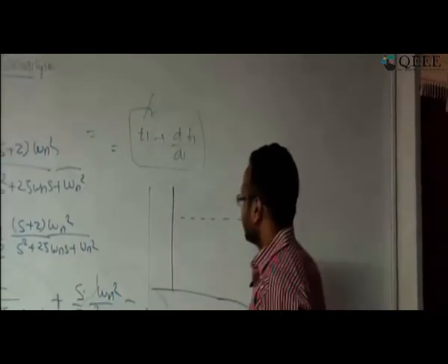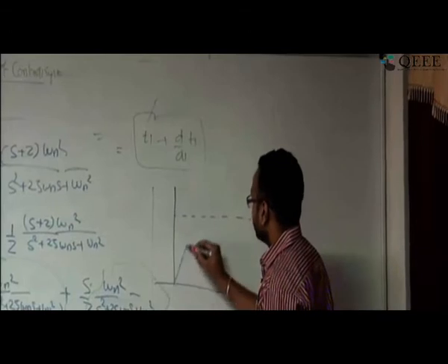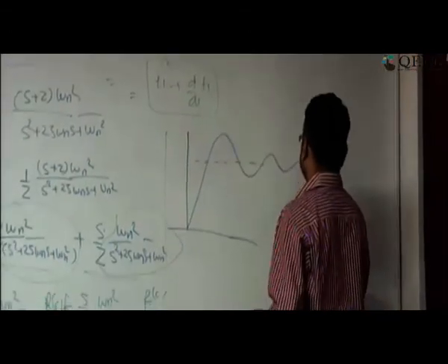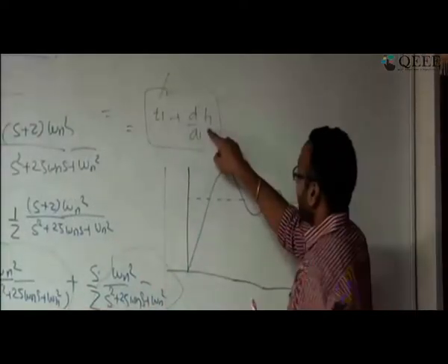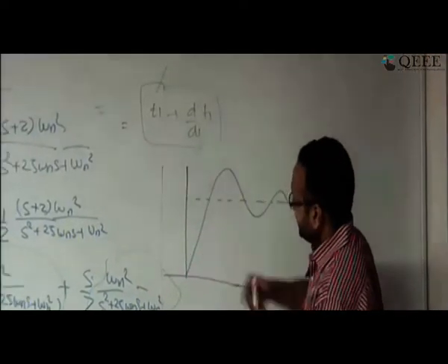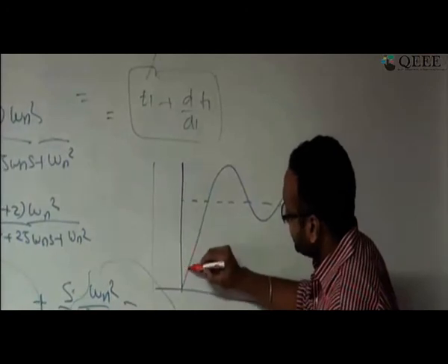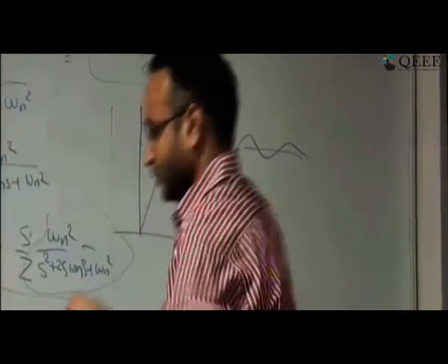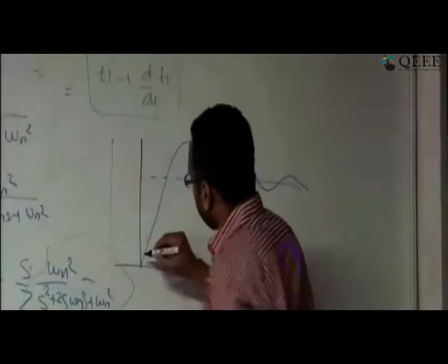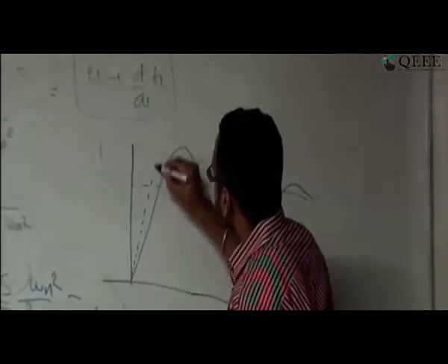This is the standard second order system, and you are giving a standard input signal, so you know the response is going to be like something. Because of the second term, the actual response is going to be this plus the derivative of this term. So I will get something like this, in black marker. Now the response is going to be something like this.